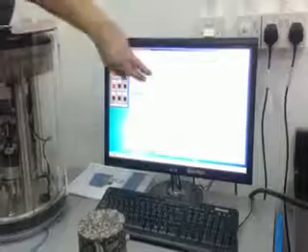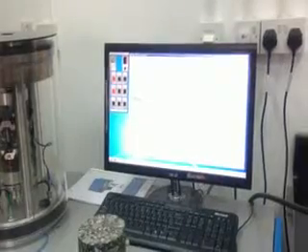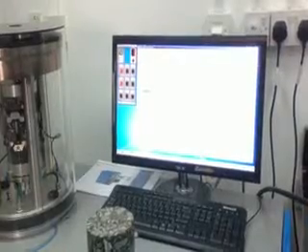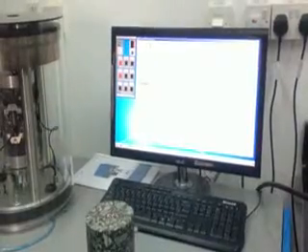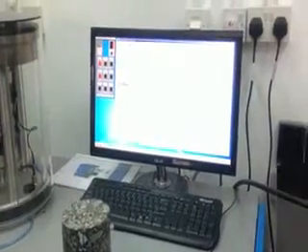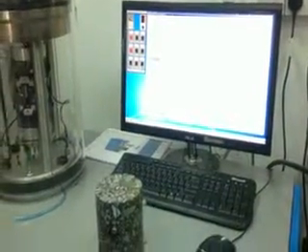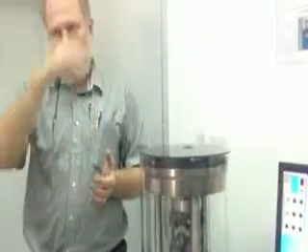Yeah, so if you untick that, then it can be adjustable. And also, the standard says they want to target 100 microstrain, but it can be quite difficult to get exactly 100, so they specify a range. As long as your strain is within 85 and 115 microstrain, the standard says you can accept that data run. So it typically tries to target 100 microstrain. You may only get 95, or a little bit more, depending on how your material reacts. As long as it's within the range, that's fine.